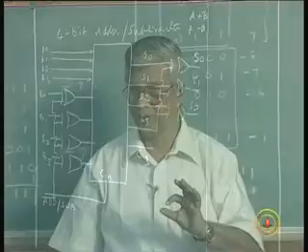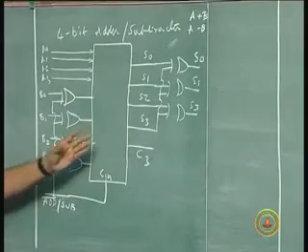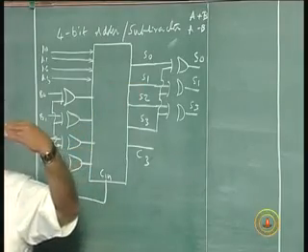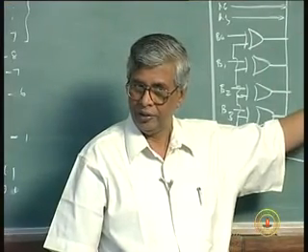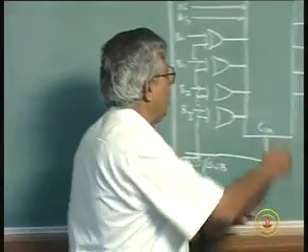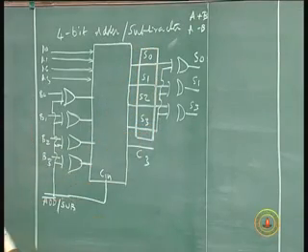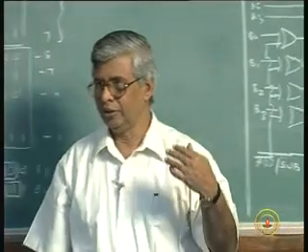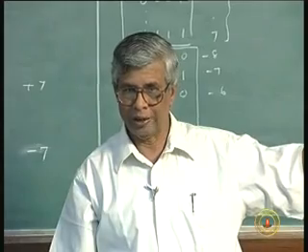Magnitude alone. You don't need it actually, as I said. We would like to keep it in this form, because later on when we go to the next computation, again you have to get the 2's complement representation of the given number. So it's good enough to have this result. But in case you want the magnitude of this number, take the 1's complement and then you have to add 1. I need one more adder to this.